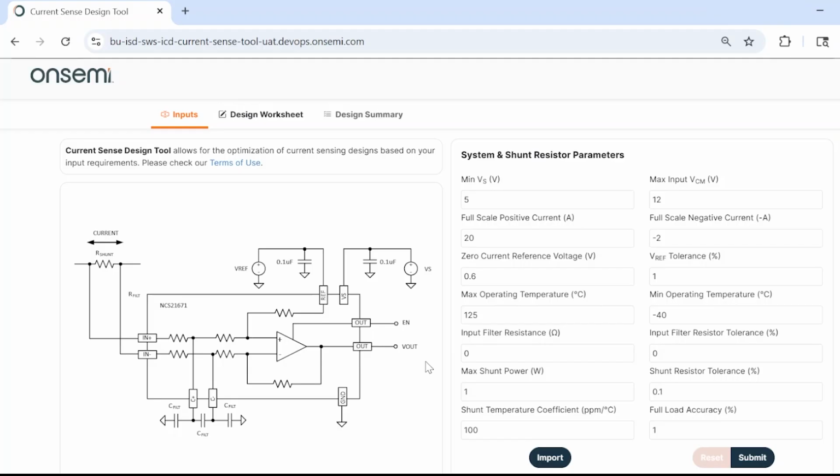And then in the next section, you're going to see that you can easily add the intended resistor values and see how they affect your boundary condition and error curves. And you can tweak those resistor values and refine your design. You will often see this resistive filtering come into play in applications such as motor drive and switching power supply applications, where series resistors are added again for filtering purposes to help with the EMI and input filtering.